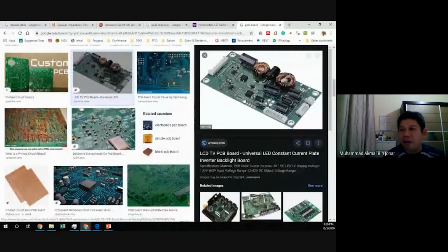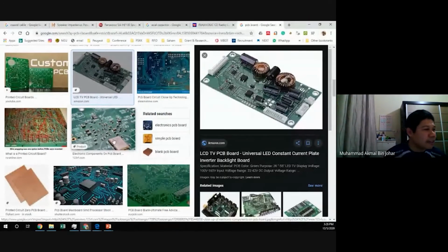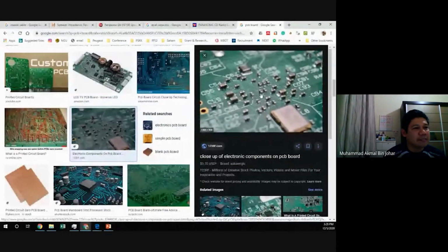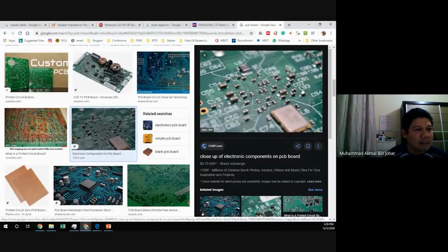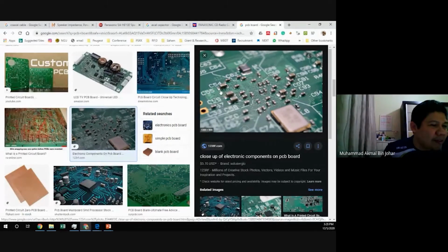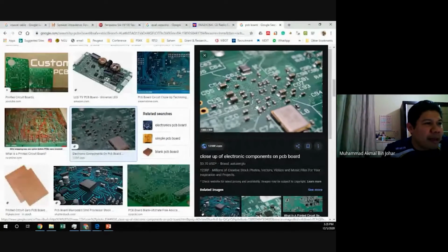This is an example of SMT, or surface mounted technology. This is also a capacitor or resistor. If the label is C, that is a capacitor, C93 is capacitor 93. So all these are capacitors, you see. A resistor will be even flatter.